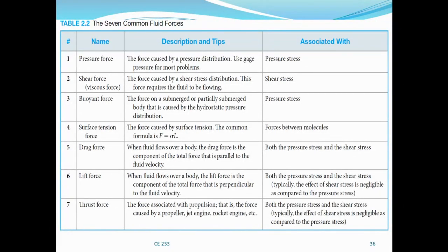And this is associated with both the pressure stress and the shear stress, though typically the effect of shear stress is negligible as compared to the pressure stress. Though the shear stress is also very important because it affects the viscosity, the no-slip condition, which we are all going to explain.